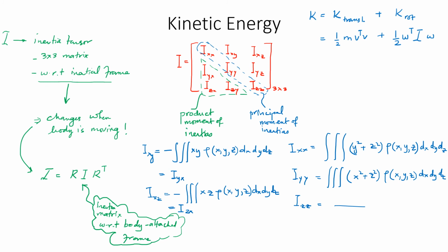So in this particular arrangement, you can use two kinds of moment of inertias, one which is called principal moment of inertias, and the others which are called product moment of inertias. Principal moment of inertias are going to always be present, but product moment of inertias may be equal to zero when you have regularly shaped bodies.